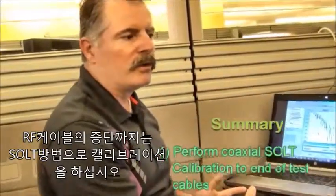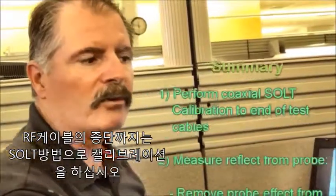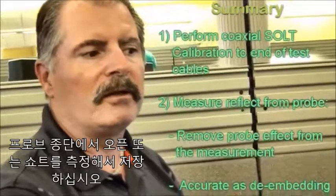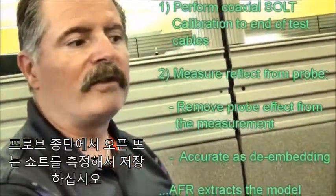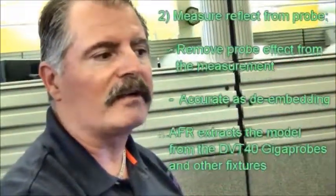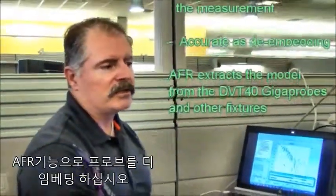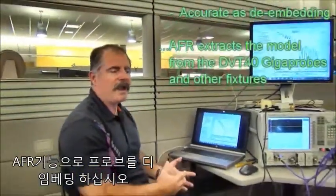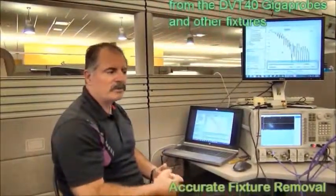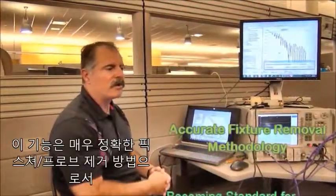We're able to first do a coaxial calibration to the end of the test cables, and then, by just simply looking at a reflect of the probe, we're able to remove all of the probe effect, which is just as accurate as a de-embedding, because AFR allows us to extract the S4P information of the probe, which is the model. And so this is a very accurate methodology.